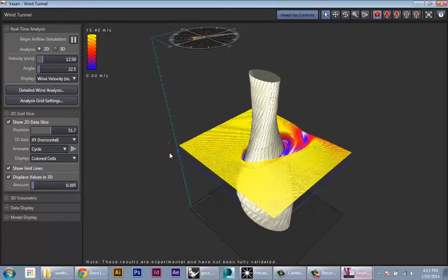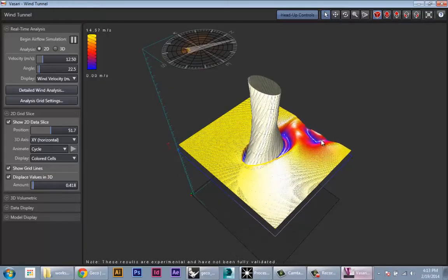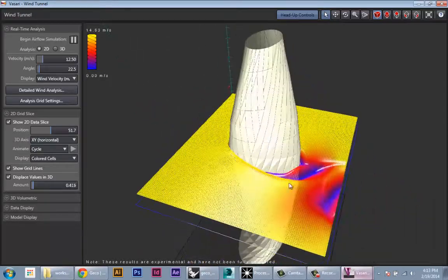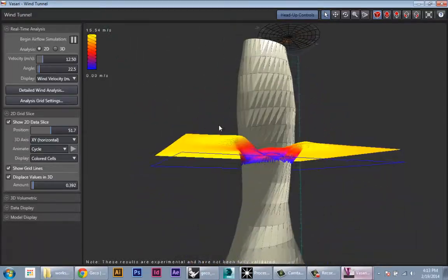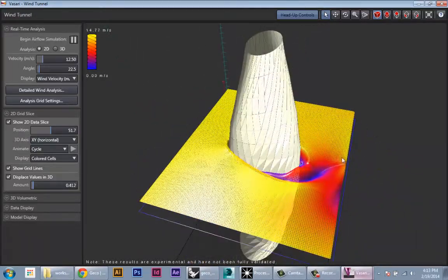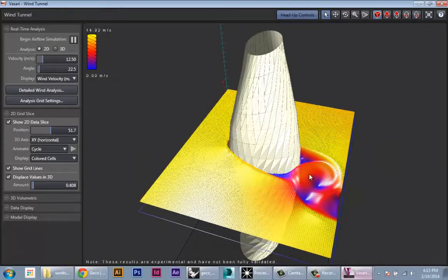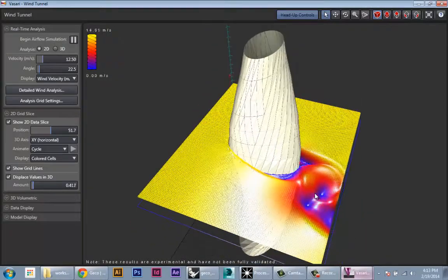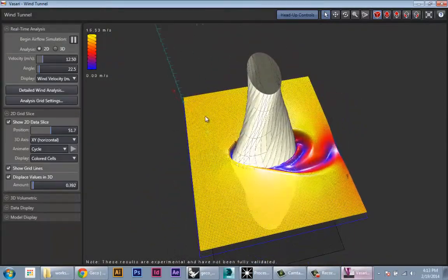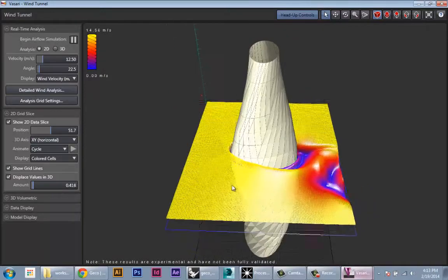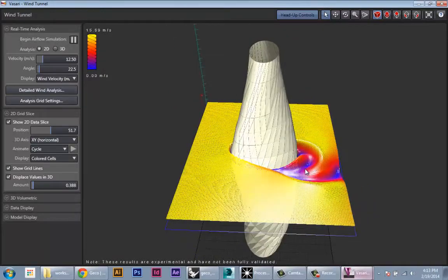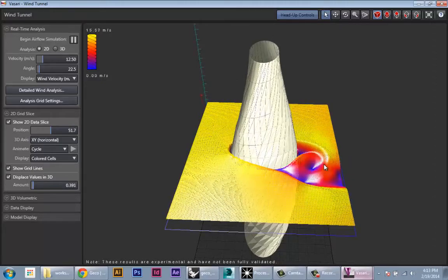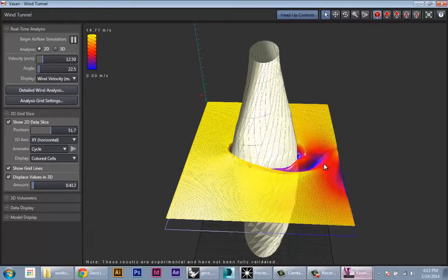It's just sending wind vectors through that space and seeing how they deform or how they behave. And the deformation here reflects the data in analysis, which is the wind speed. Okay, so deformation doesn't mean that the wind is moving down or up. It's just a visualization of the wind speed. And here you can see that everything's kind of this yellowy orange, and then as the wind goes around the building, it gets slower, and in some cases, when it gets channeled, it'll actually speed up.